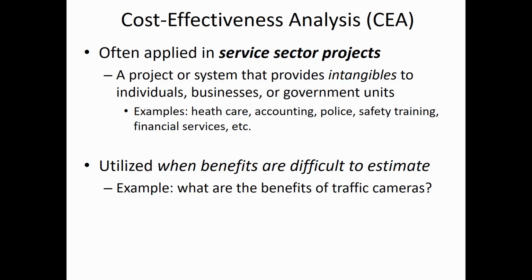If you're able to assign a dollar value for a reduction in delay in the case of traffic, then you can calculate benefit cost. In the case of flood protection, if you can translate reduction in severity and frequency of floods into some sort of a dollar value of the property that's been protected, then benefit cost is a good way to analyze flood protection projects.